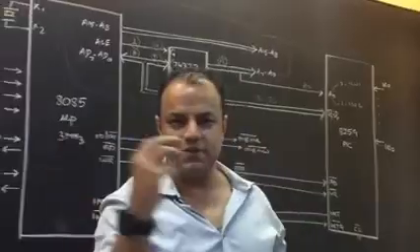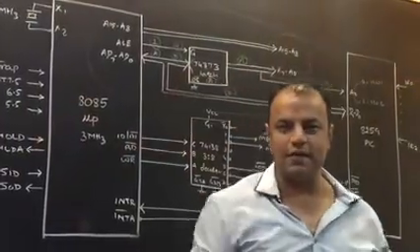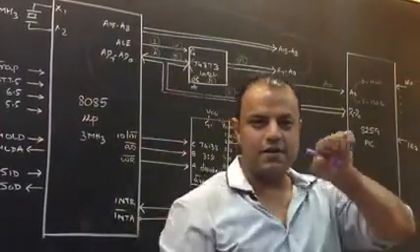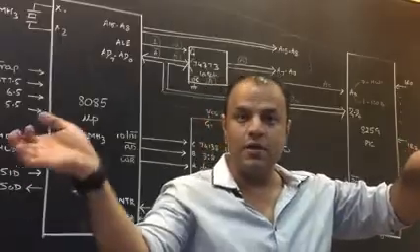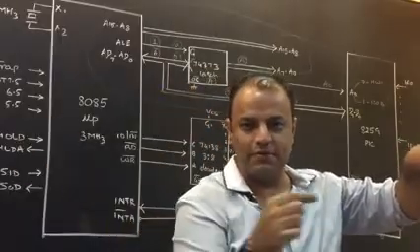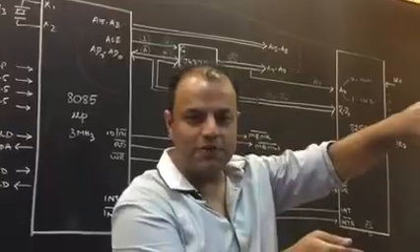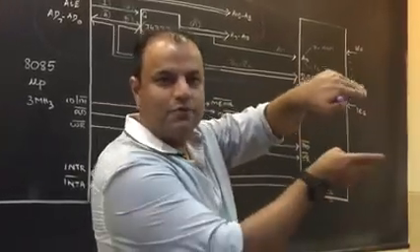Take the multiplex bus, give it to the latch, give the ALE signal to the gate of the latch. When ALE is 1, the latch will capture the address, and the latch will produce the address now. The bus carries data, ALE is 0. Data will not enter the latch, data will come from down. The latch will produce the address, and the bus will carry data.